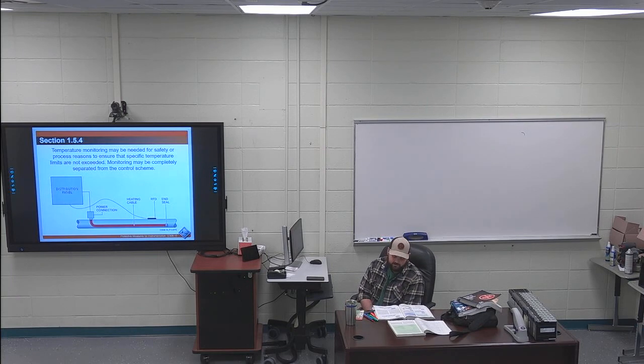First sentence is highlighted. Temperature monitoring systems continually monitor the temperature of the pipe with resistance temperature detectors, or RTDs. See up here on the board, or at the bottom of your page 11, you've got an RTD on this pipe, and then the heating cable. So the RTD senses the temperature of the pipe, and then sends back to the distribution panel, which turns on and off the power connection based on the temperature.